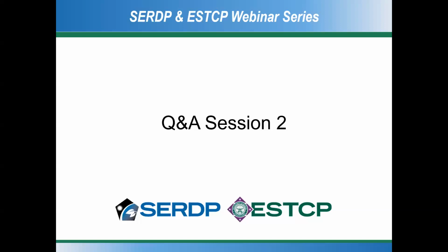Hi there. Yeah, so when we've been looking at implementing this method, the pulse exposure method, at these different DoD locations, we've had to make a lot of assumptions, but ultimately implementation is going to have to be on a site-specific basis, where we're examining rainfall or discharge durations for a given site, or discharge like outfall specifically.